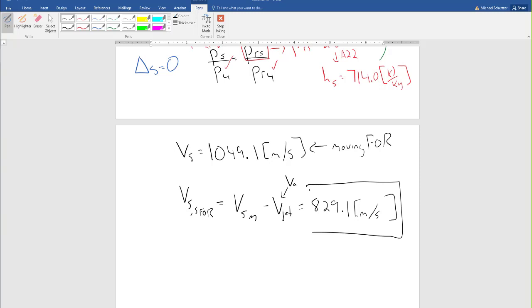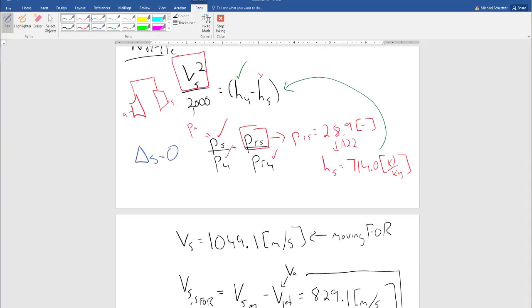If you go through and look at the video, certainly in the long version of the video in the thermal lecture series, and I think also in the thermo short, I do a side-by-side for each state showing how to fix it with a variable specific heat, which we did here, but then also a constant specific heat. It's essentially the same problem. If this was a constant specific heat problem, basically every time we used this equation, instead we would have used T over T is equal to P over P to the (k minus 1) over k, right?